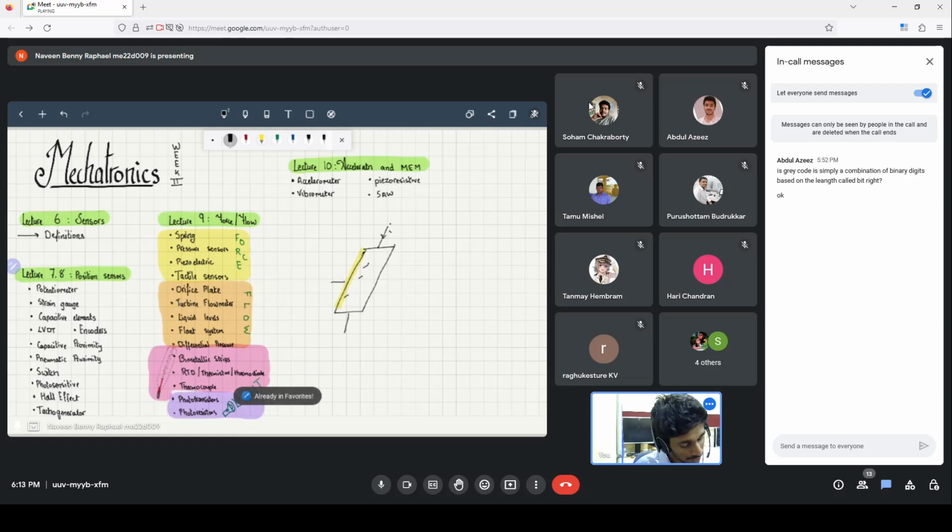And so because one region has more electrons than the other, this essentially forms a form of a capacitor, and because it forms a capacitor, we can find the potential difference across these 2 points. Therefore, we can measure the presence of a magnetic field based on this potential output we get.